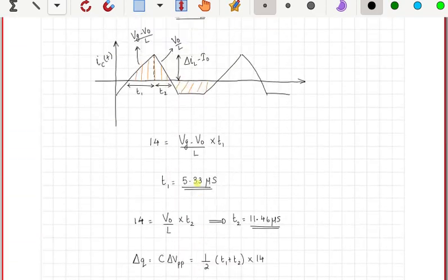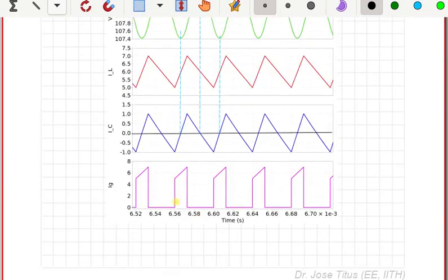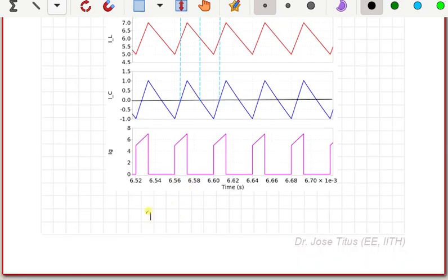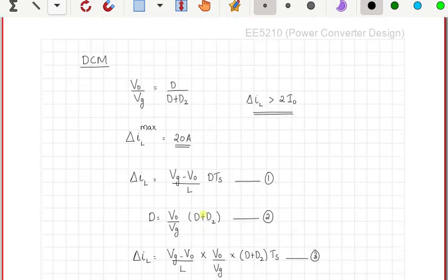Even in CCM we have this type of waveform where we have the current flowing only for some time, and therefore if you look at the average component in this case, it is also going to be equal to 1.9 amperes. That does not depend on CCM or DCM. But you will have a smaller harmonic component when you are operating in CCM, because you can see the peak current goes up to 7 amps only, and also the conduction is for a longer duration. You have conduction happening for 0.3176 times Ts instead of 0.1905. So here the harmonic component is going to be lesser in any case.